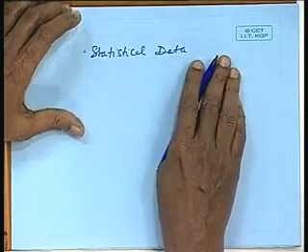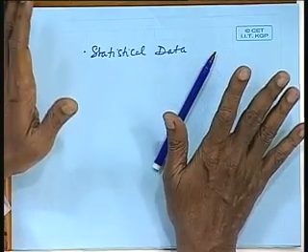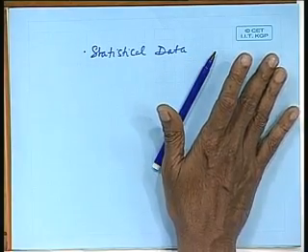One thing you must have understood by now is that all these series that I have mentioned are all non-bulbous forms, and today we have ships with bulbous forms. Therefore, present day ships perhaps will be better than most of the series ships, and therefore, this data cannot be used with any reliability for modern ships. They tend to overestimate the resistance if you use it for a modern day ship.